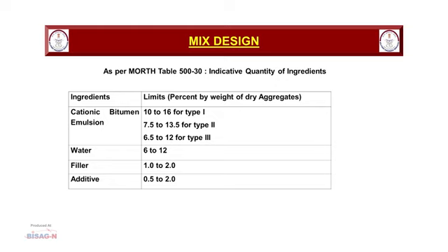These aggregates, bitumen emulsion, water and additives, including set control additives, will be proportioned by weight utilizing the approved mix design such that the slurry seal mixture has proper workability and permits traffic within 4 hours without leading to raveling.